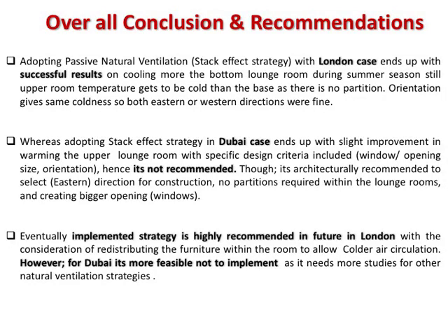To conclude, for the scenarios conducted for the Dubai and London models, the overall conclusion and recommendations are the following. Adopting the passive natural ventilation stack effect strategy in the London case ends up with successful results in cooling the bottom lounge room more during the summer season, and it will be even better considering the allocation to either northeastern or northwestern.